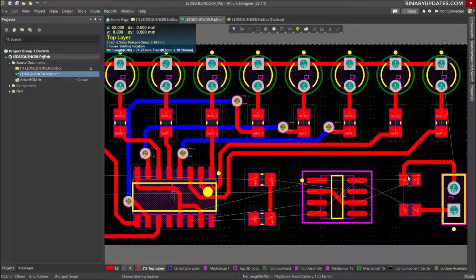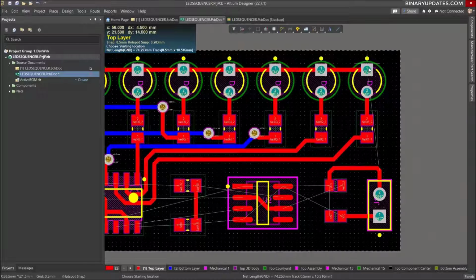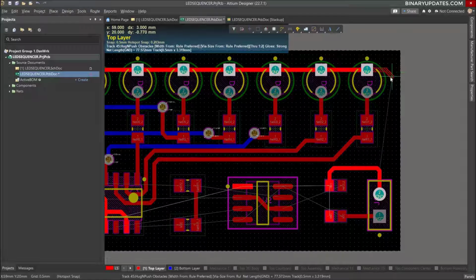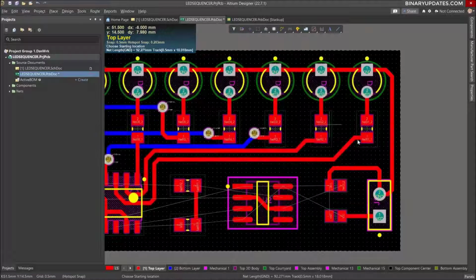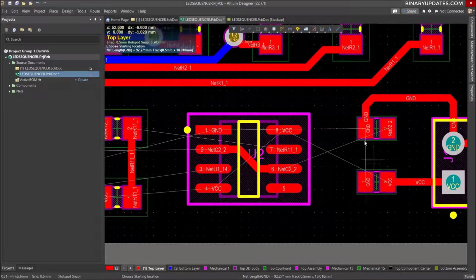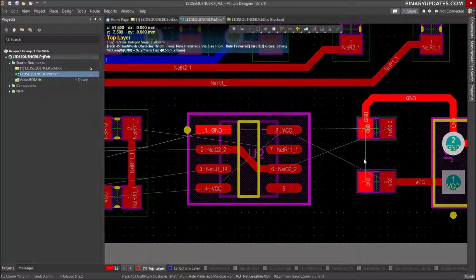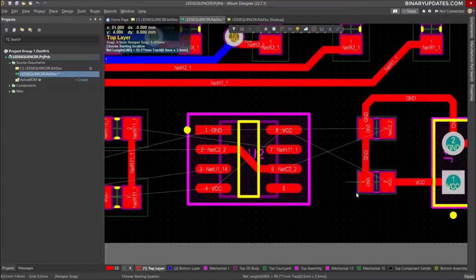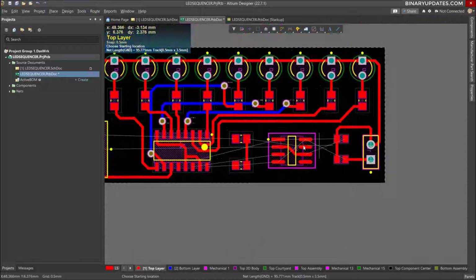And what else? Okay, you see here there's a yellow net. We can also optimize. This is the easiest one, so I don't mind this to finish. Now it's gone. So this part looks cool. I can just connect these 2 resistors' ground pin, and now that's also gone, so looks pretty neat and clean.